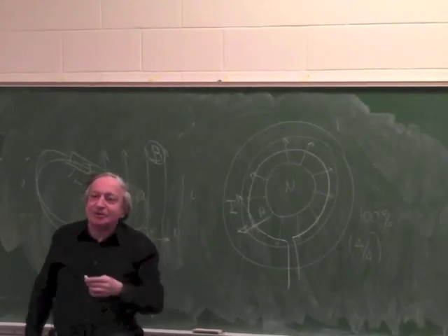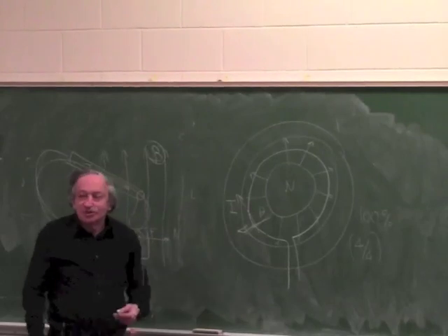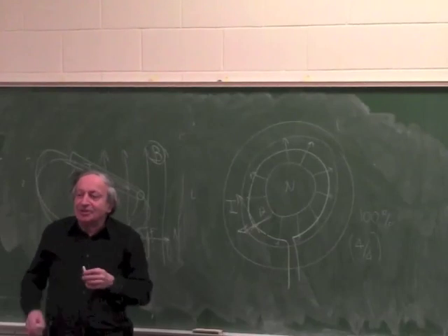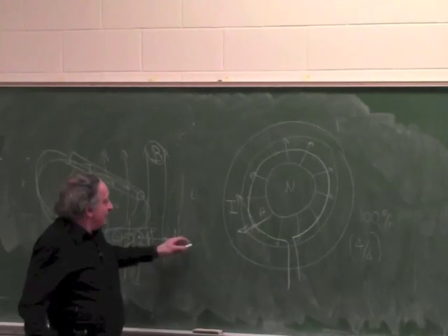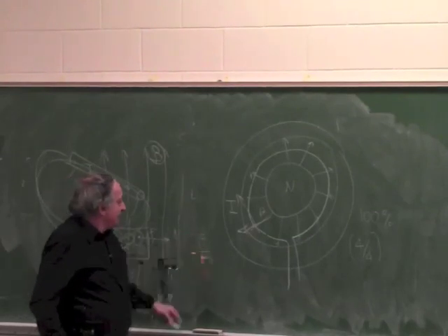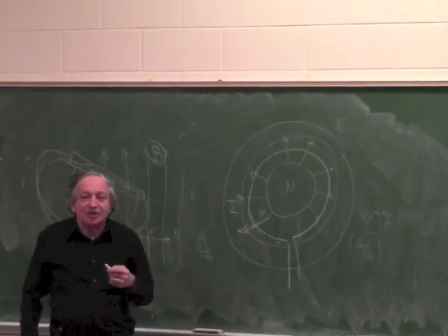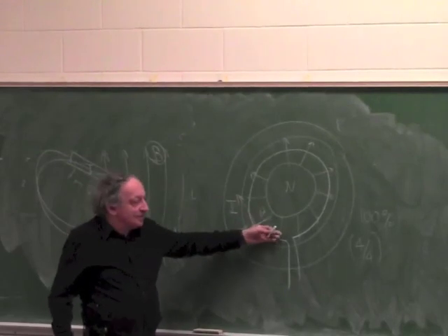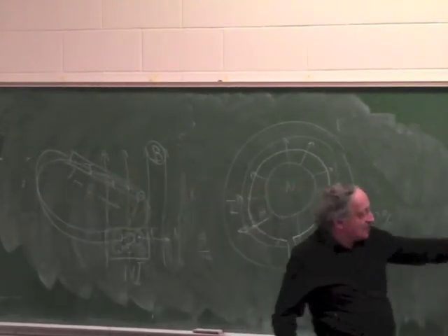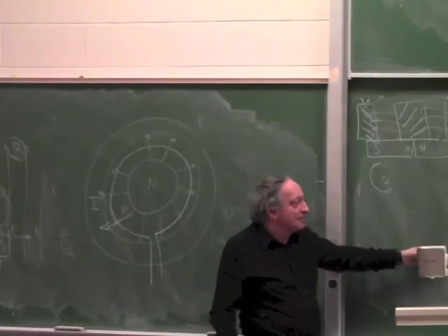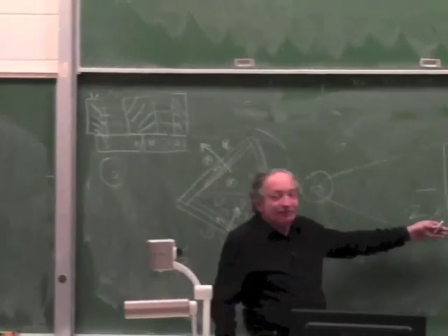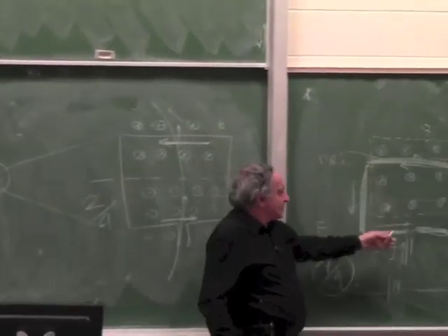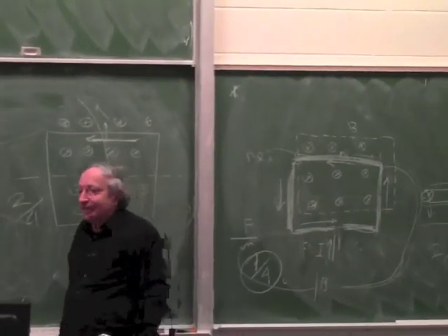So in the disk drives, they wanted it rotary, so this actuator wasn't suitable. A, because this is more like a cube. B, because it's not rotary. But if we talk about F over m, the maximum force to mass, which determines acceleration, this is a 100% efficient actuator. The disk drive is a 66% efficient actuator. Reversing the magnet is a 50% efficient actuator, and a plain loop in the field is a 25% efficient actuator.